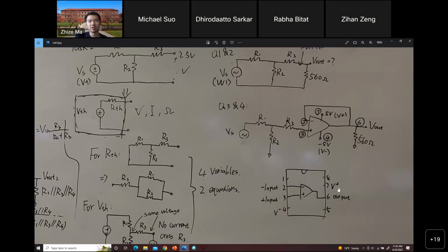The power supply pins are very important here. If you accidentally invert pin 4 and pin 7, which means you connect the negative power supply to pin 7 and the positive power supply to pin 4, that will burn the chip. I'm not sure what happens with the AD2, but if you use benchtop equipment that will make the chip smoke. If you are using the AD2, you will probably see a current overflow warning in the software. Make sure pin 4 and pin 7 are connected correctly.